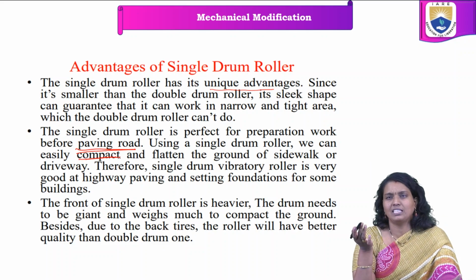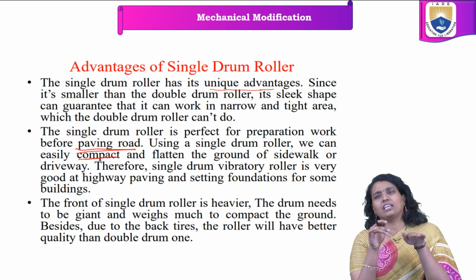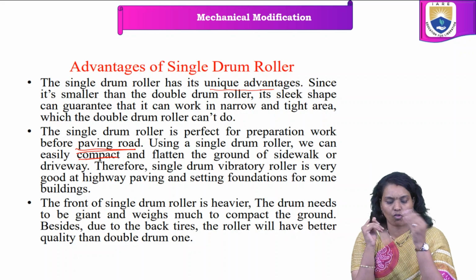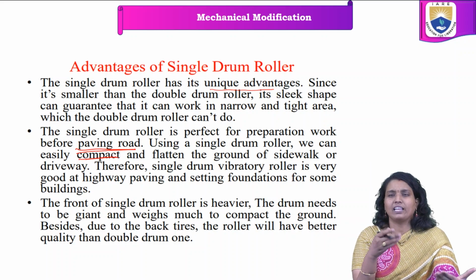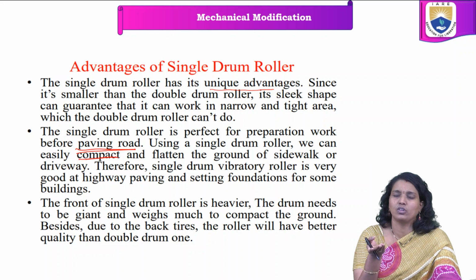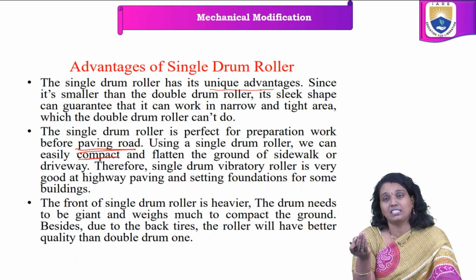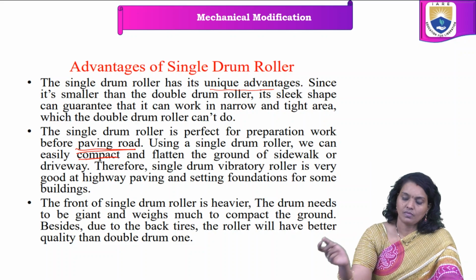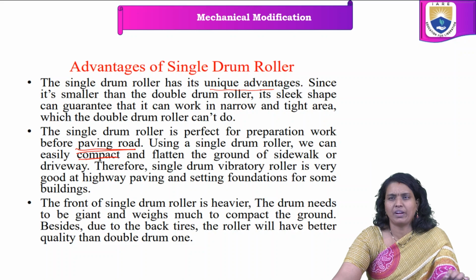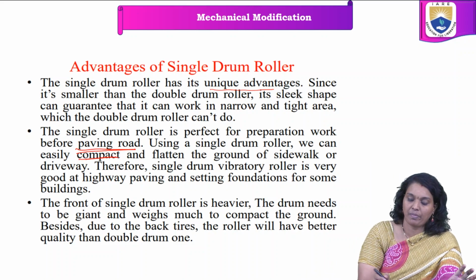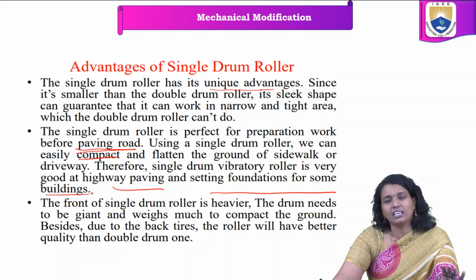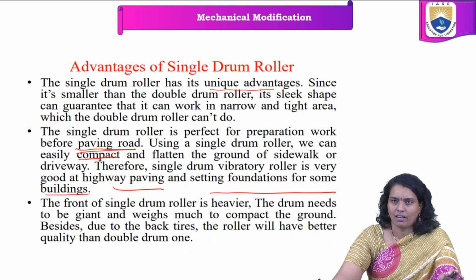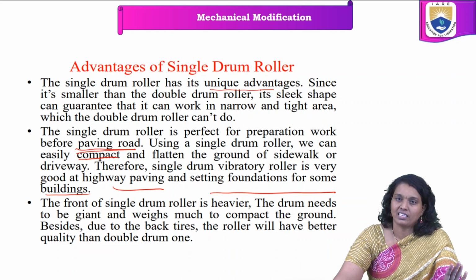Compaction is very easy, and flattening the ground for sidewalks, walkways and driveways becomes easier, and the use is very simple. The single drum vibratory roller is very good at highway paving and setting the foundation for some buildings. So for setting foundations it is also helpful, because of the size. The front of the single drum roller is heavier.